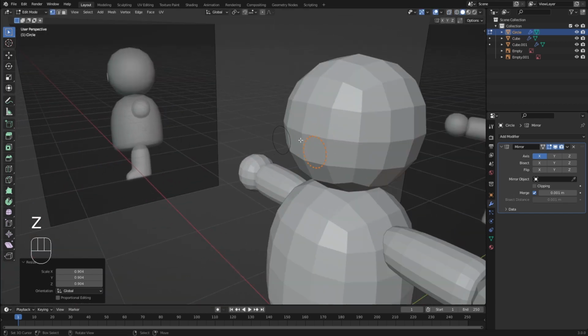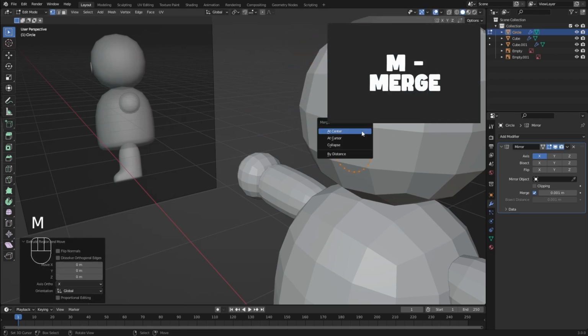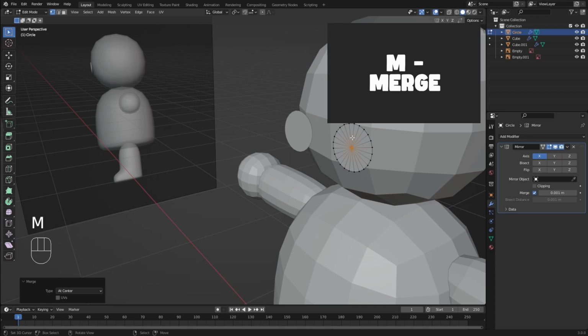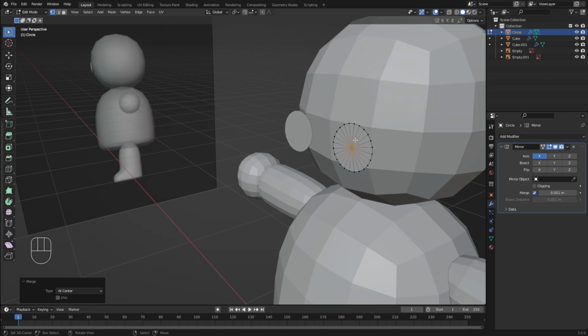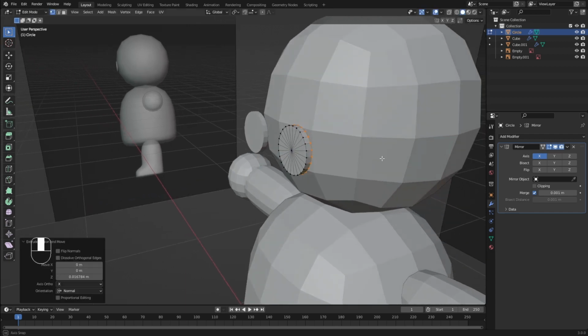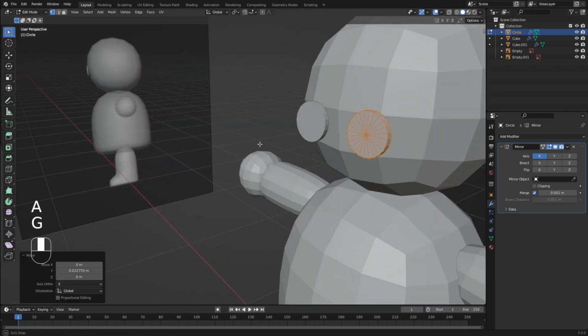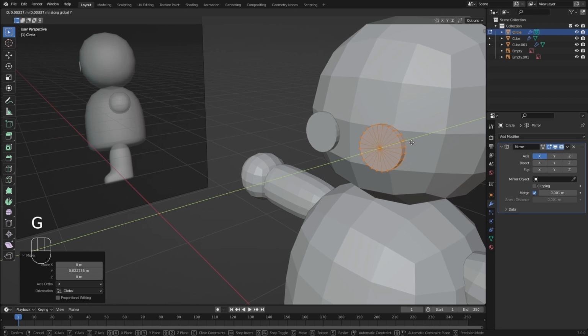And in order to add faces to this, because this is currently just vertices and it's transparent, you can either do F, but this is not good geometry, and game engines usually don't like this. So what I usually do is press E to extrude, right click to put it back, M to merge at center, and now we get these triangles which work better with game engines. Press A to select everything, E, and then just move it back so we get this nice little thing. Select everything and just move it a tad bit back so it's not clipping through the object, but it's still on it.